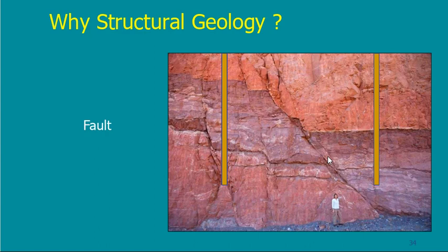So I should not put my building on top of a fault. But if it is an active fault, maybe I have to go away a few kilometers. But if it is not active, maybe I would go a few meters. So it depends on the activity of the fault. So this is the link that we need to understand between geology and geotechnical engineering.